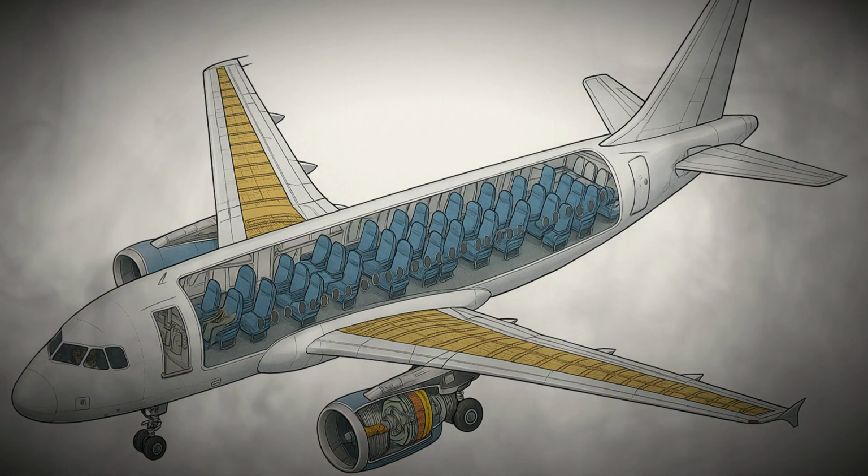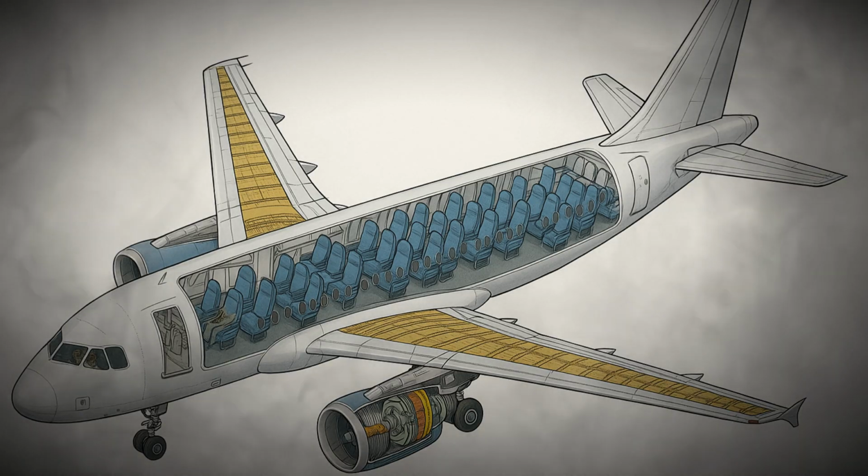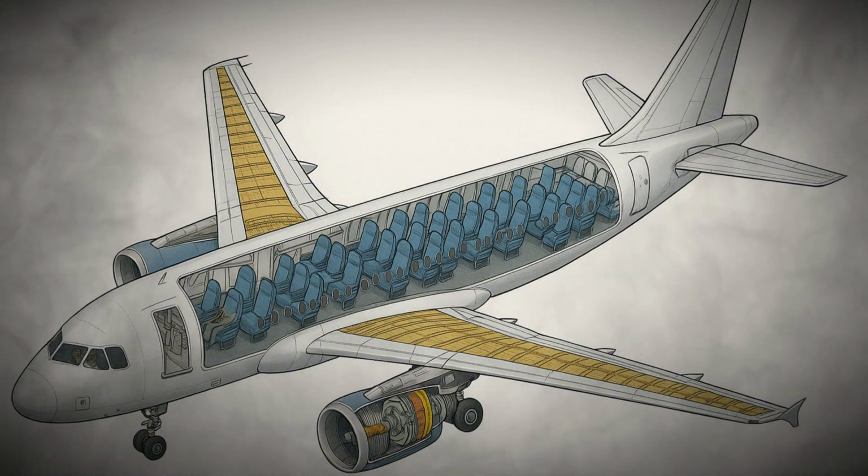On final approach, the airplane must be precisely aligned with the runway centerline, and the descent rate must be controlled. Pilots adjust pitch and power continuously to stay on the glide slope. Crosswind landings require special techniques such as crabbing, where the airplane is flown slightly angled into the wind, or slipping, where rudder and aileron inputs counteract drift.